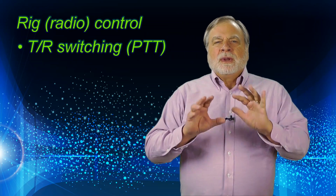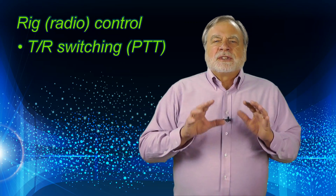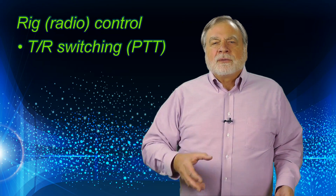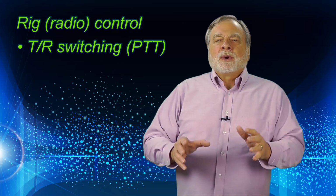Now, we approach the potentially tricky challenge of rig control. There are two aspects of this. First, being able to tell the rig when to go into transmit and when into receive. Note that you don't absolutely have to do this, as you can set up the rig's VOX system to put the rig into transmit whenever it hears the tones from the sound card output. But I prefer that the software do the transmit determination and use the rig's push-to-talk system properly.